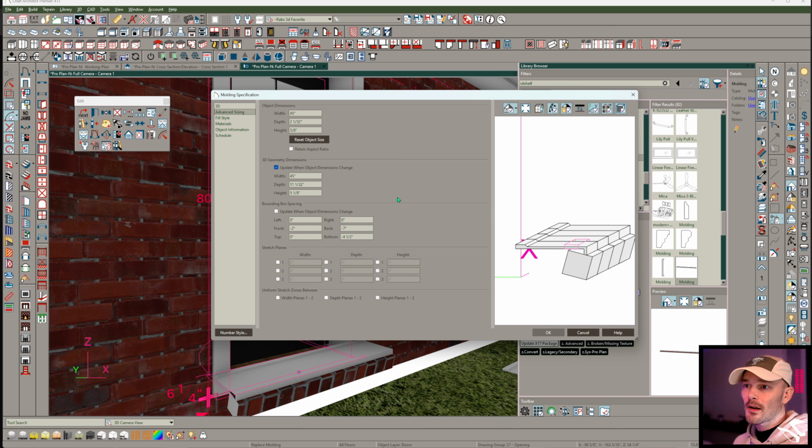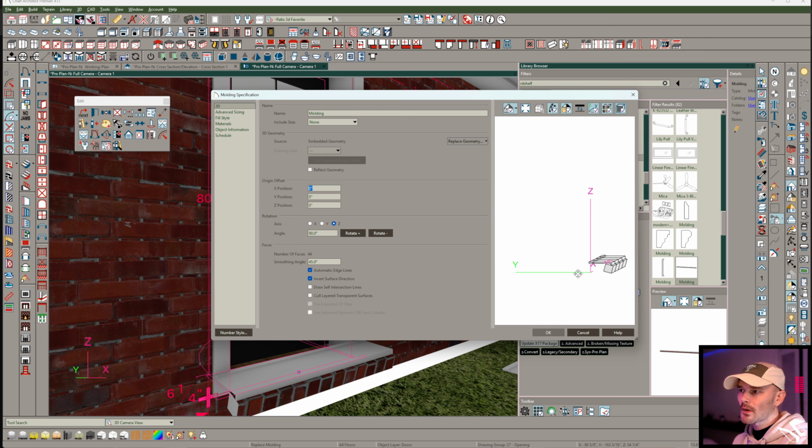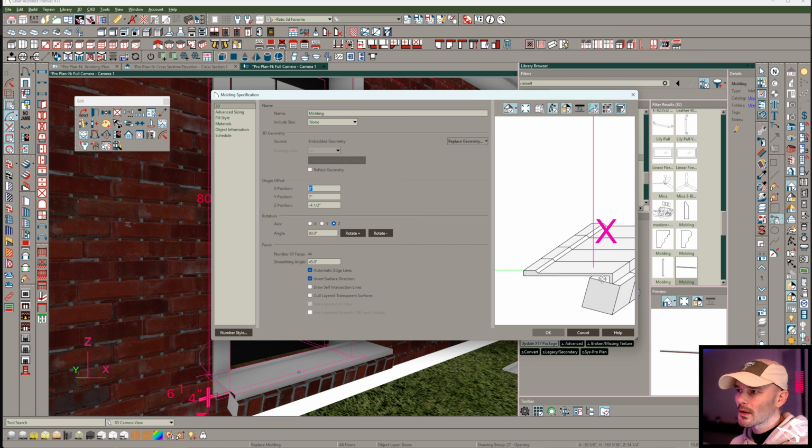All right, with that in mind, I think we get to just say, okay, 7 and 4.5. Come back to the 3D menu. This is the positive Y leg, right? So we need to move positively 7 inches, and we need to move the Z in negative 4.5. So that's in a negative. There we go. So now that origin is right where I want it to be.